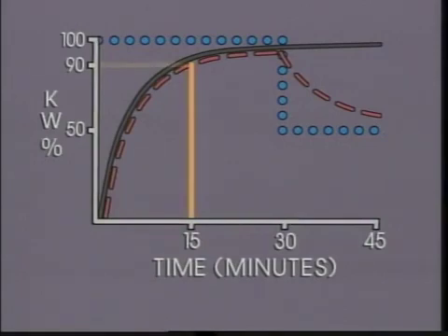And in 15 minutes, the thermal response is only 90% of the load. Notice that the thermal response doesn't near 100% of the load for quite some time after the 15-minute interval. This is where the term lagged comes from when referring to the response method of thermal registers.